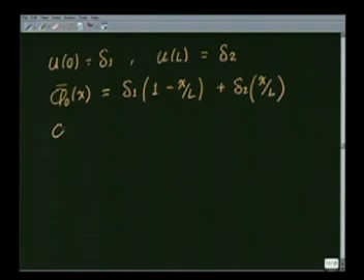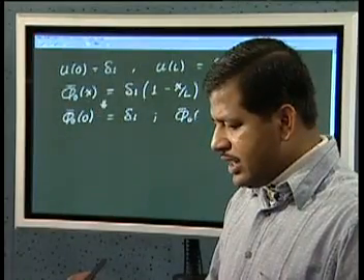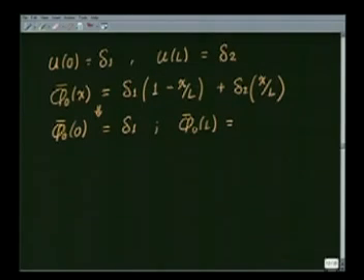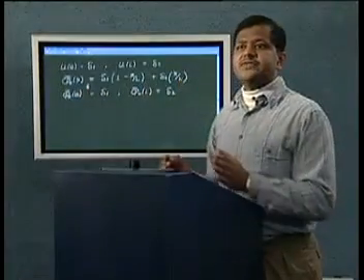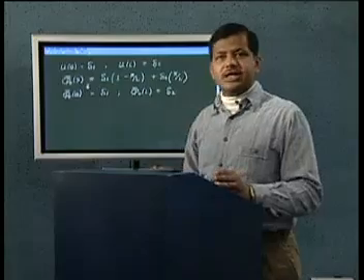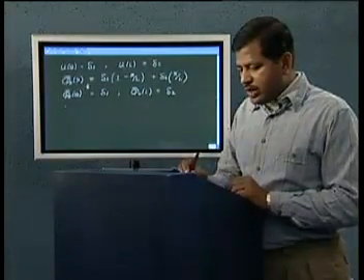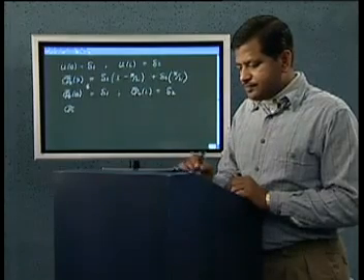So this gives me phi 0 bar at 0 is equal to delta 1. And phi 0 bar at x equal to L: if you substitute, the first expression goes to 0 and what we get here is 1. So this will be equal to delta 2. So phi 0 bar satisfies the given geometric constraints exactly at the 2 points. Now the question is, how do I choose the remaining phi i's?